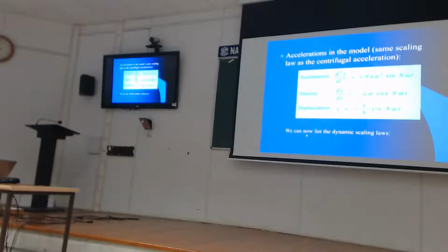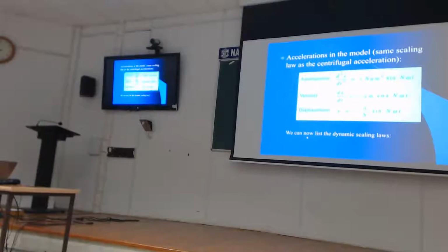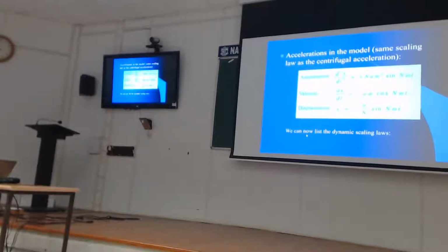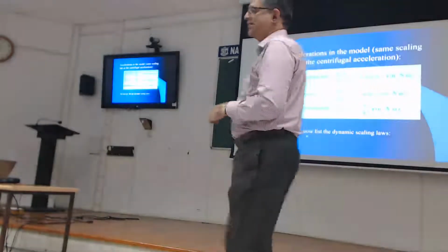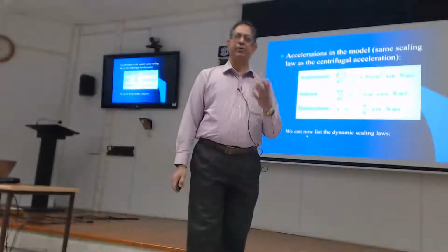Now we also notice that the displacement amplitude A is now being divided by n, which is right, because yesterday also all length parameters must be scaled down by a factor of n. So by increasing the acceleration by a factor of n, we got the right displacement as well. The only problem is that this frequency has to go up by a factor of n.